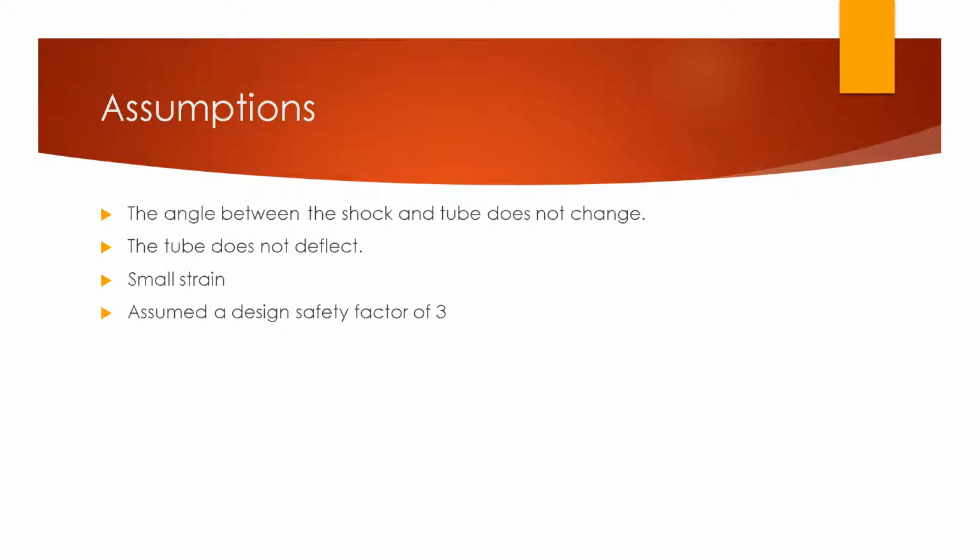Some assumptions involved in this project were the angle between the shock and tube does not change, the tube does not deflect, assume small strain, and assume a design safety factor of 3.